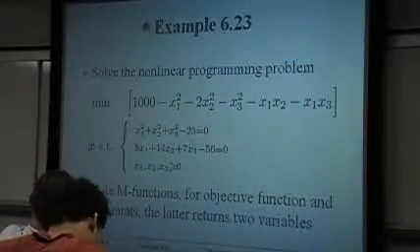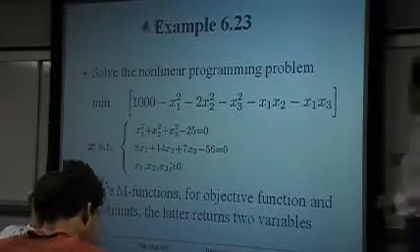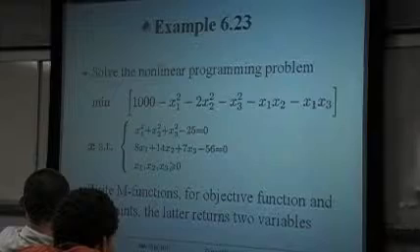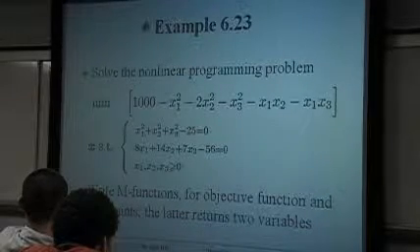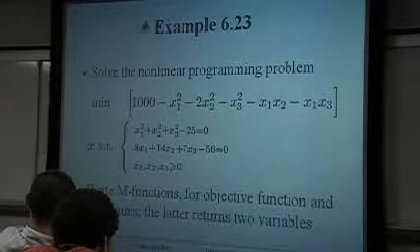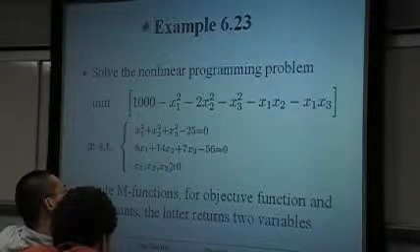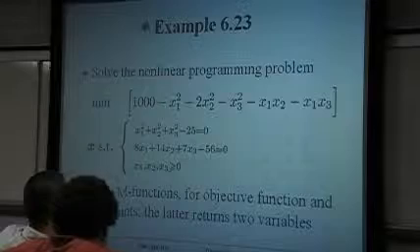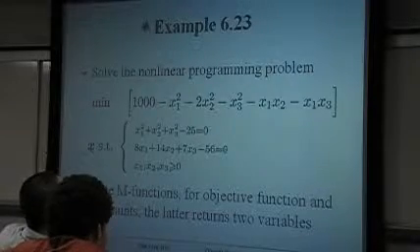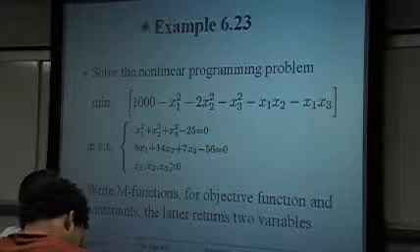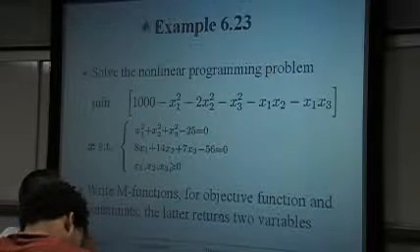For this particular example, there is no nonlinear inequality constraint, so we have to assign C equal to an empty matrix. We have to write this one, we cannot omit it. If there isn't an inequality constraint, we still have to assign the variable C, because we have to return it, so we assign it as an empty matrix.